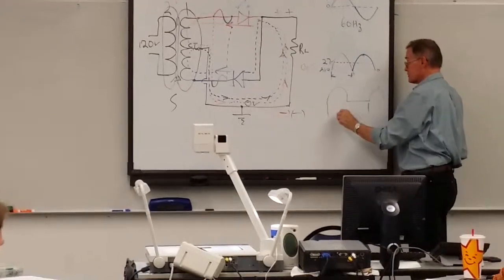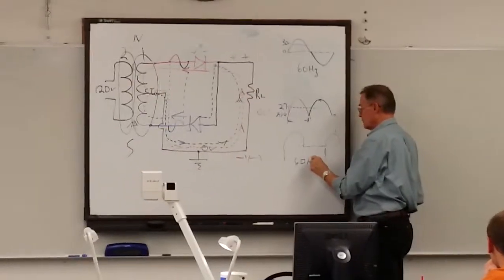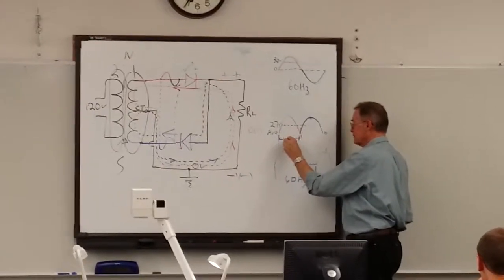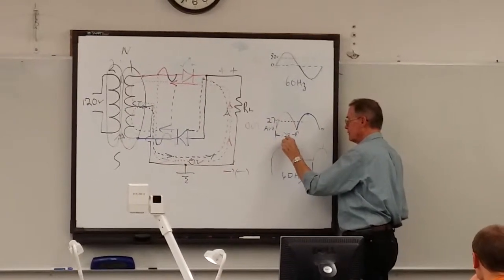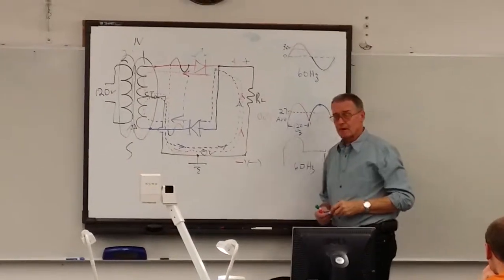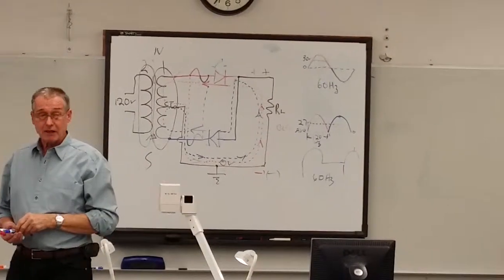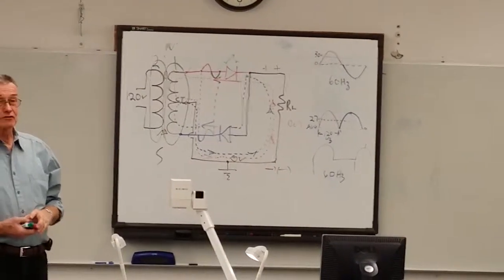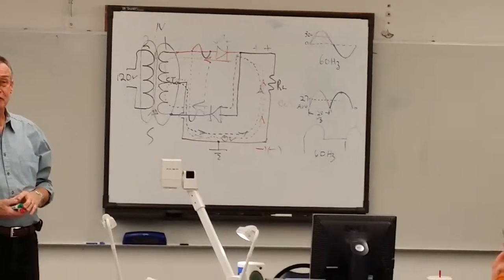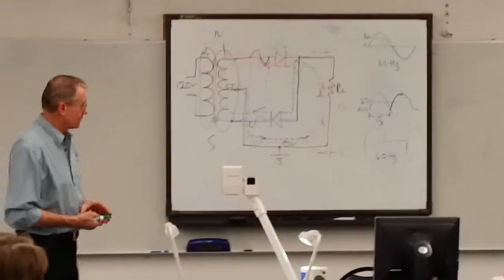So this frequency is 60 hertz. And what's this frequency then? It's twice that. That means you get 2 waves. Now, the only time that's an advantage is if you're going to filter the power supply, which we'll talk about a little bit later. Mainly most of next week, but